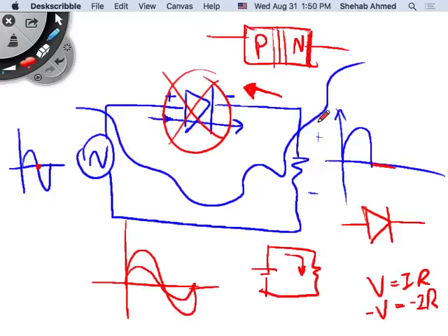The depletion layer was being filled with these charges, the positive charges on one side, negative charges on the other side, to create this larger barrier voltage, to put the device in reverse mode, or shrink the depletion layer so that the diffusion current can go through and the device would conduct. This required some time, right?